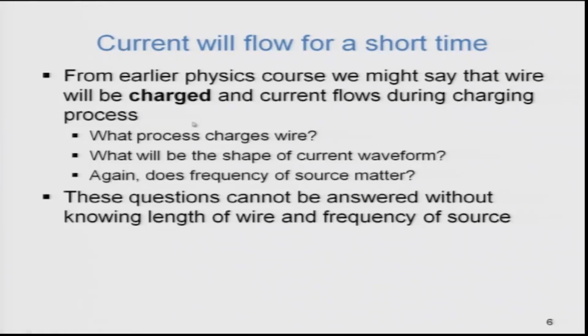So, what is the charging process? What process causes charging of the wire? And how would the charging current look? Even if it flows only for a short duration of time, what would be the charging current waveform, or the shape of the current waveform? Again, does it depend on the frequency or on the waveform of the voltage source that you are connecting? These are the questions which unfortunately cannot be answered by circuit theory, and certainly these questions require us to know the length of the wire and the frequency of the source much more than what I have specified here.